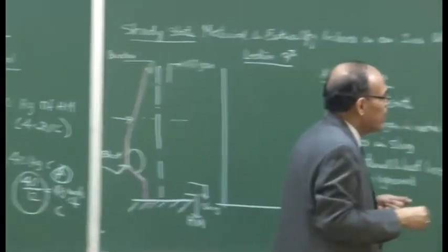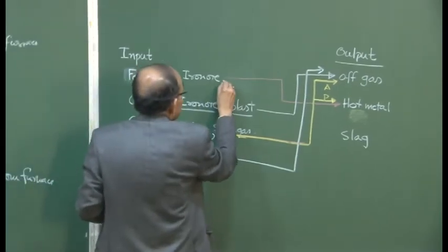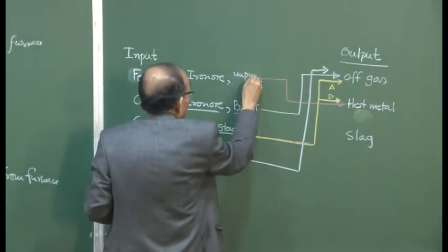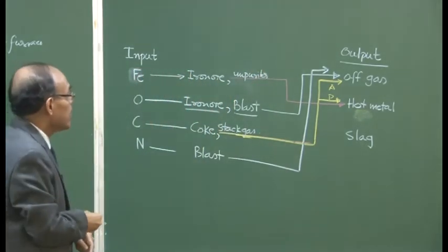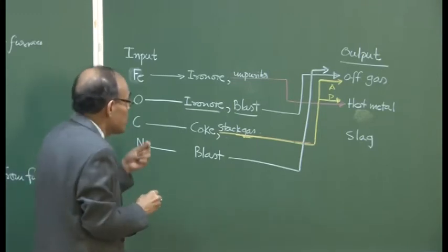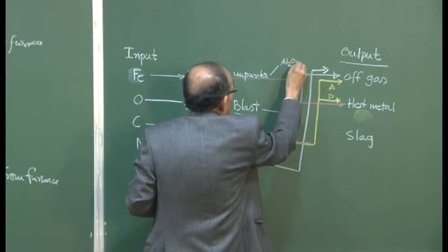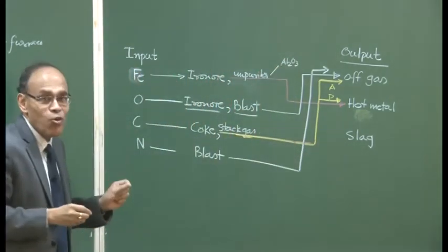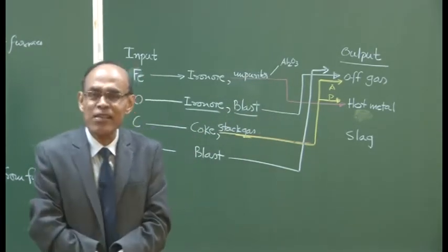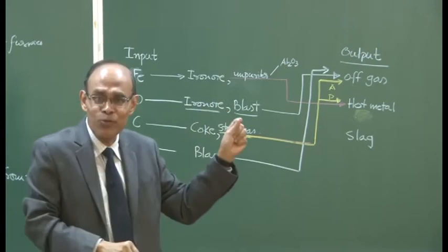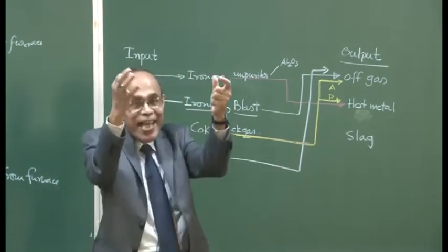We must understand that in the input, if you consider for example iron ore which contains some impurities, and for the time being let us discuss two different impurities to explain the concept. One impurity is Al2O3. I know that the Al2O3 will undergo no chemical reduction in the blast furnace, except that the entire amount of alumina present in the ore is going to be just absorbing heat.